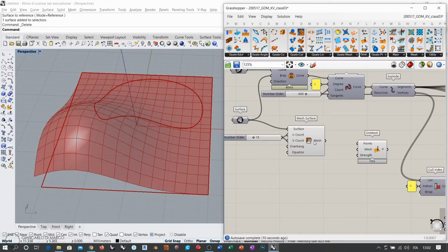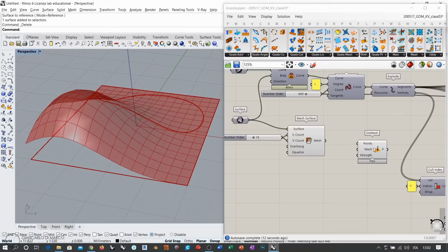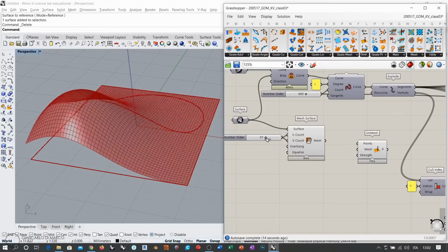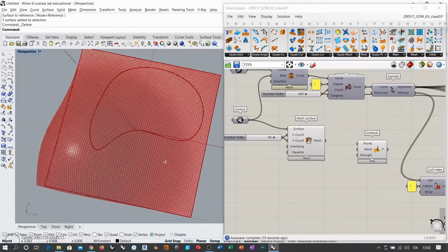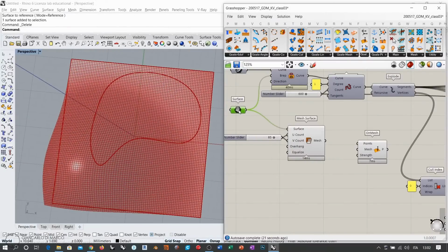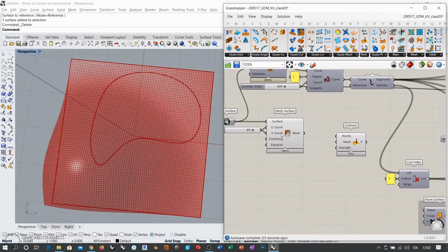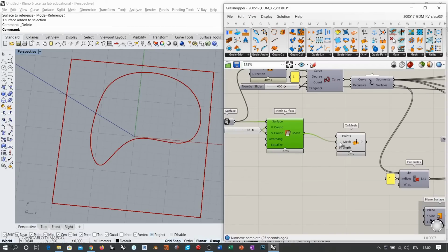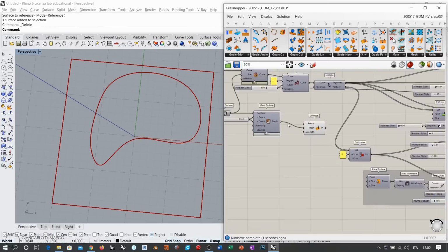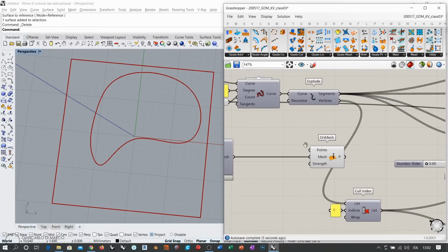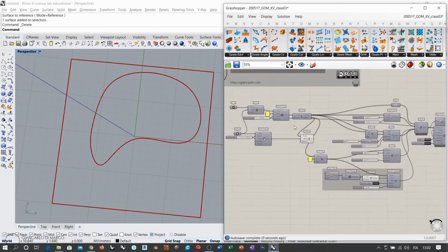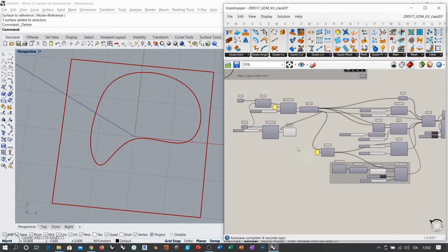It's going only to be used for projection, basically. So I would prefer to create quite a high resolution mesh in order to have a better representation of my original organic surface. Okay, and therefore I'm going to use this mesh as the on mesh target. And in the end, what I want to keep on this mesh are the vertices of the organic shape that we have here. And so I would take these, that would be the alternative goal.